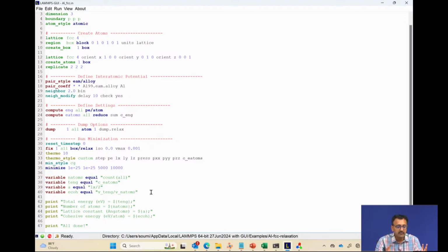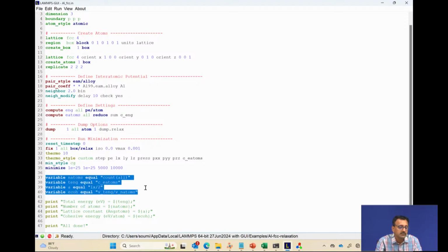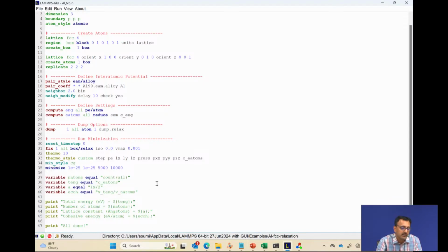Now that you have set this up and are ready to start, the final aspect is what quantities or parameters or properties you want this code to determine from this minimization algorithm. We want to calculate the lattice parameter. So you set a variable A to which you're recording the measured lattice parameter. That's something we're really interested in. We're starting with 4 angstrom, but we want to see what it adjusts to. Does it agree with the known lattice parameter for aluminum?